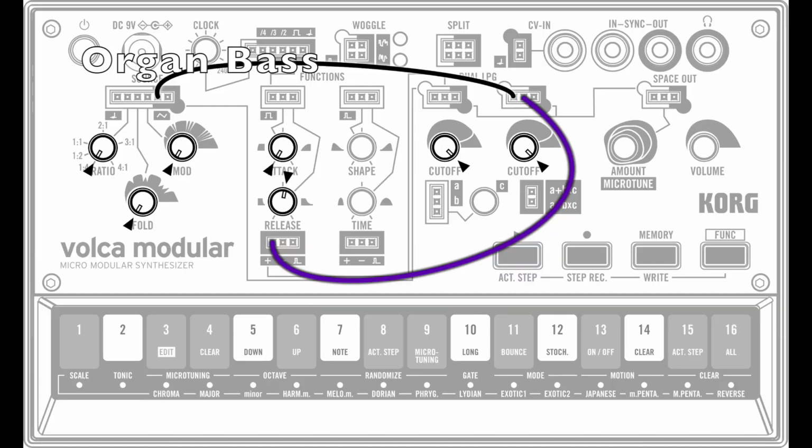The modulator wave is fed to LPG2 via the source modulator wave output to the LPG2 signal input, and LPG2 gets a volume envelope which is the same as the volume envelope used for LPG1, because we're patching the function 1 positive output to the LPG2 level input. The LPG1 level input already has a default routing from the function 1 positive output, as we can see by the thin line on the front panel.